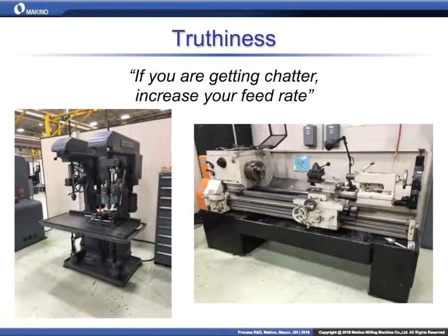But we also talked about within the regeneration of waviness, your chip thickness is proportional to how much cutting force is being observed by the cutter. And if you are having a chatter situation and you increase the chip thickness, you could be making the situation worse, adding more force, or adding more load to something that's already varying wildly. That was the situation I had years ago with someone who does this. That's why I remember that quote so well. It did not work. Right.